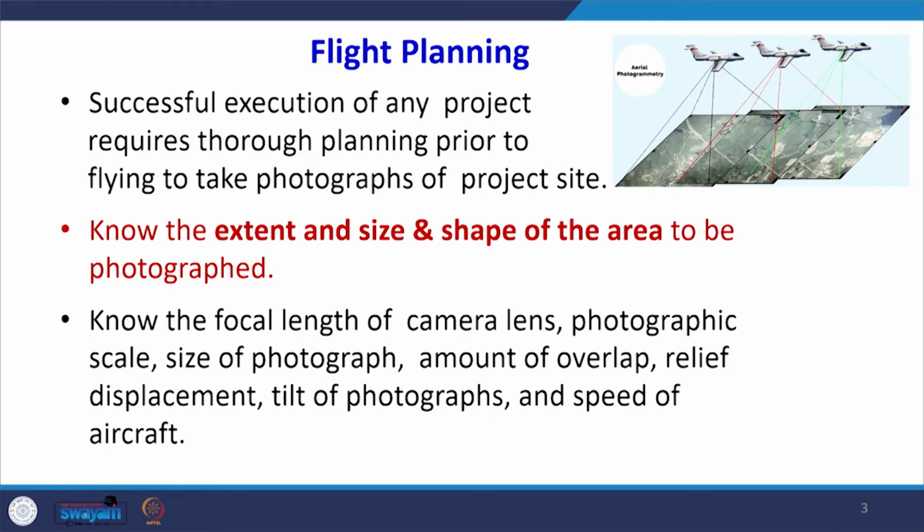Scale and overlap are also very important before we fly: at what scale the images are to be taken and what the overlap between the images will be, so that we can see a good 3D model. So, that is a little bit about flight planning. Whenever we have a project, its execution would require some photographs.